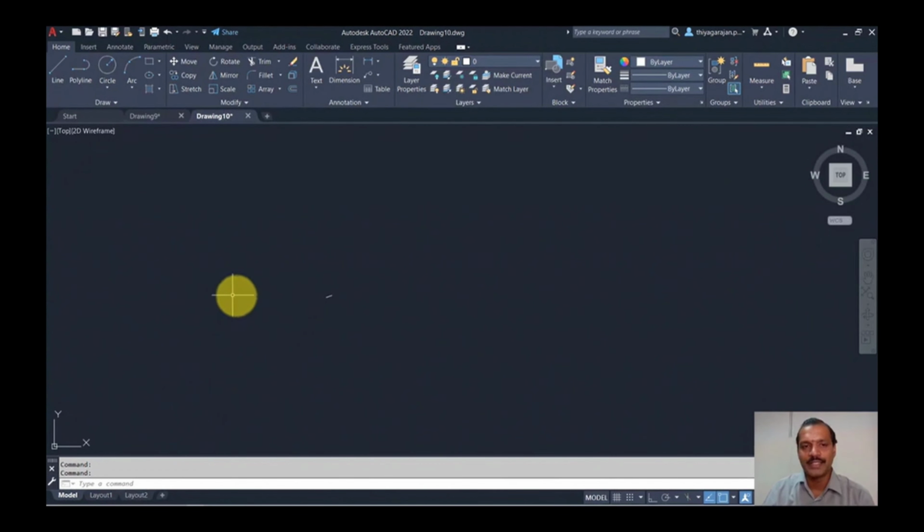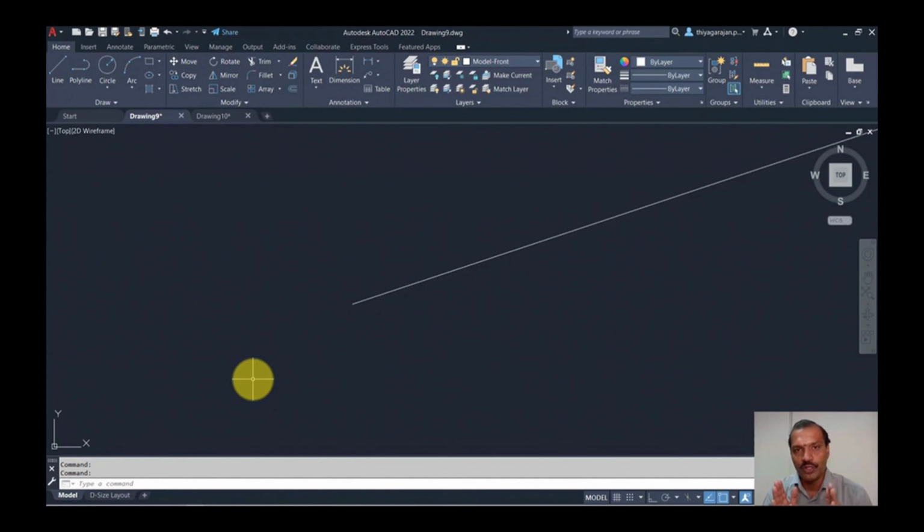It is very simple. Here the drawing sheet, the drawing area, is very big. That is why your 50 mm is very small. Here your drawing area, that means your drawing sheet, is very small. That is why your line looks very big. So it should not be like this. Before you draw, you have to decide what size your drawing will be, or choose what paper you are going to draw on.